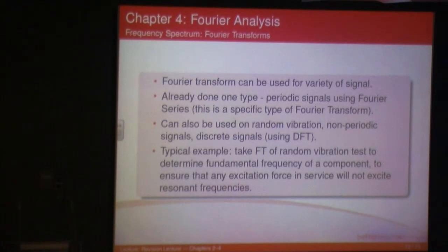And a typical example would be you have a component that you developed as part of your industry or whatever, okay, and that component is possibly going to be subject to some periodic excitation, okay. An example would be, say, I don't know, a helicopter, okay, part of the helicopter, obviously that's going to be subject to some vibration because of the rotors and stuff, but what you want to make sure is that your component is going to be able to deal with that oscillation, okay, and you don't want it to hit resonance.